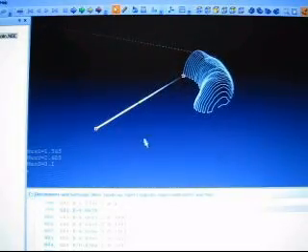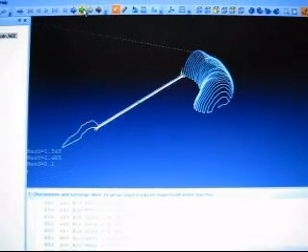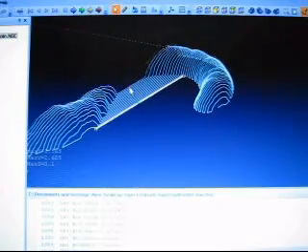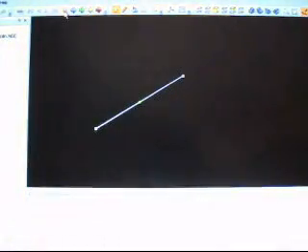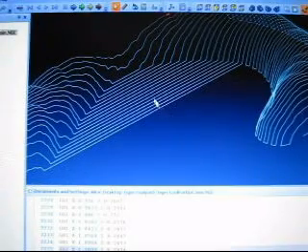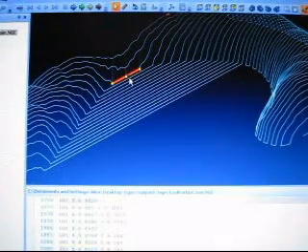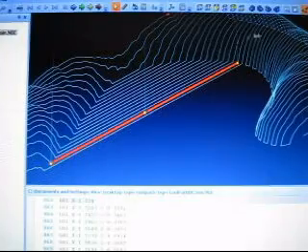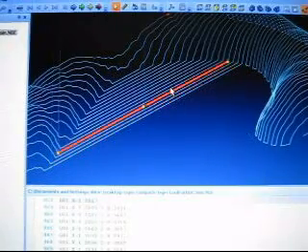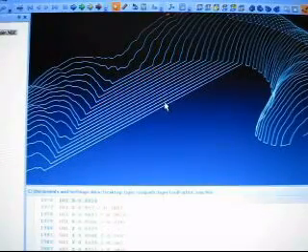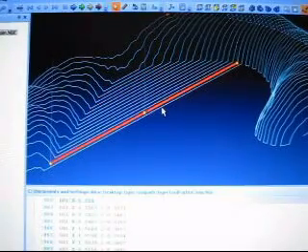I'd be happier if this section over here, see, it's going to cut a bunch of straight lines over here and so forth, and I kind of don't want that. Okay, so here we are in the area of contention. These lines, you may have noticed that I did not eliminate them, and the reason for that was I wanted this thing to scan in a predictable manner, and this is not a very difficult section to fix. There's only a few lines that I want to turn into rapid motions over here, okay?